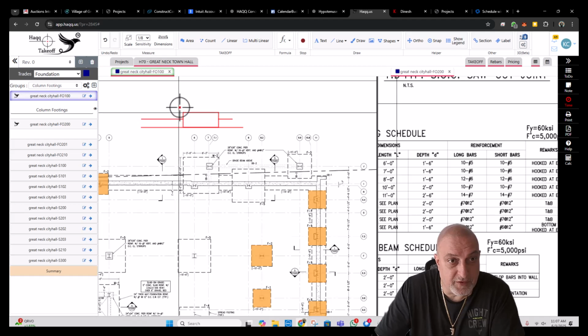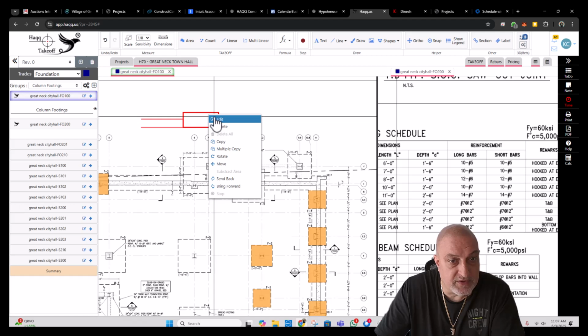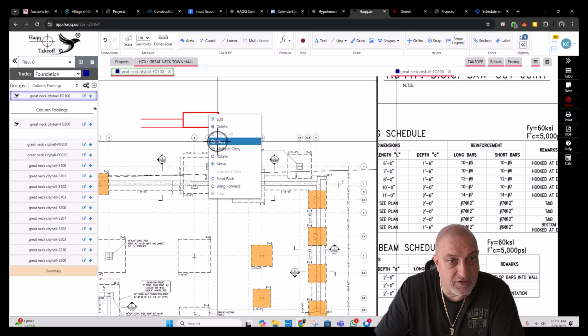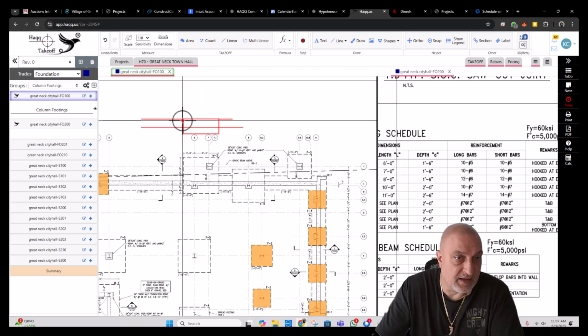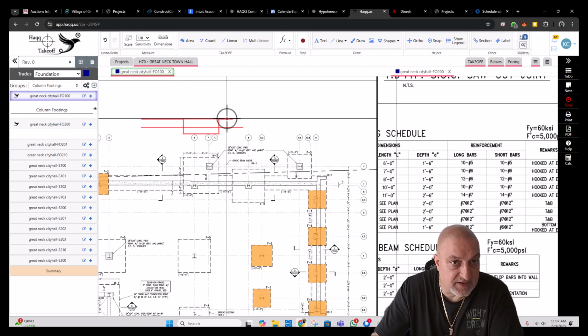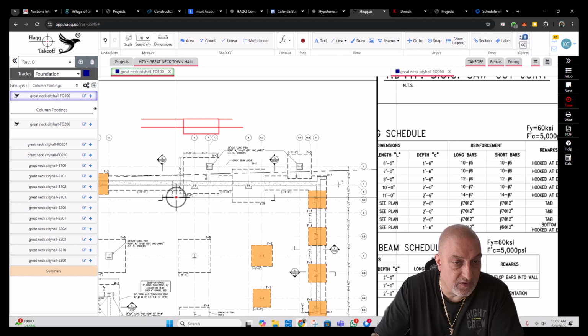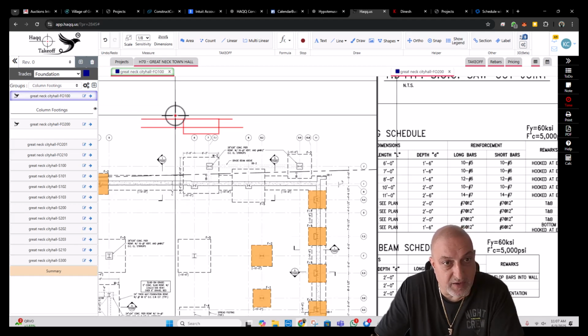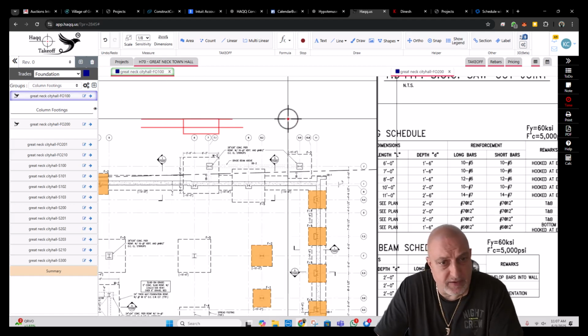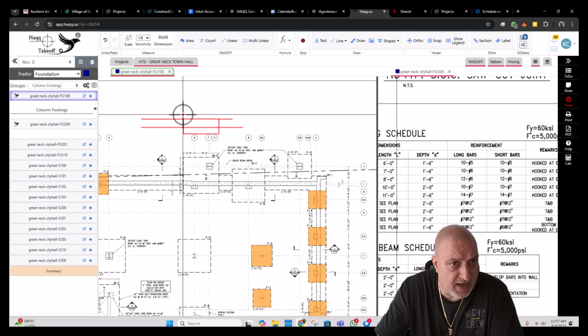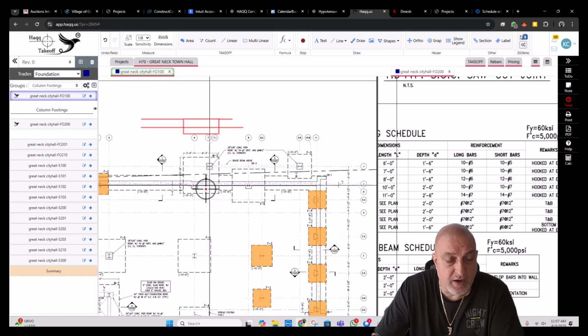If this is the case, then for your formwork for the walls, you're creating a step. We don't want to do this. What we want to do, for easy constructability, is make the top of footings the same elevation as this continuous footings. This way you can put your formwork for the walls faster. If you create a step, that will be a lot harder to set the formwork. Let's move on.